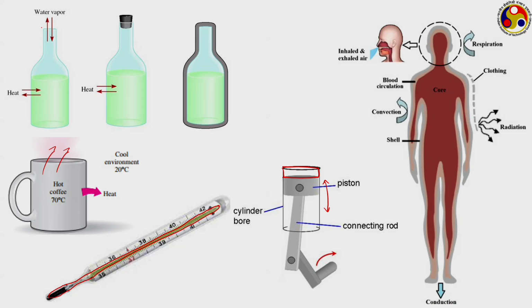Of course, because of respiration, we have air coming inside our system and also going out. So, it is actually an open system, because there is a mass interaction. Several kinds of thermal and energy interaction can take place. Because of convective heat loss to the surrounding, we may be losing energy to the surrounding. There may be conduction through the part of our body which is in contact with the ground. There may be radiation losses under certain situations, particularly through the clothing that we are wearing. Also, when we sweat, some sweat may evaporate from our body, that also leads to another source of mass interaction. So, it can be viewed as an open system.